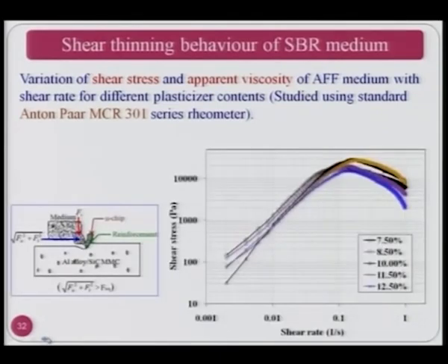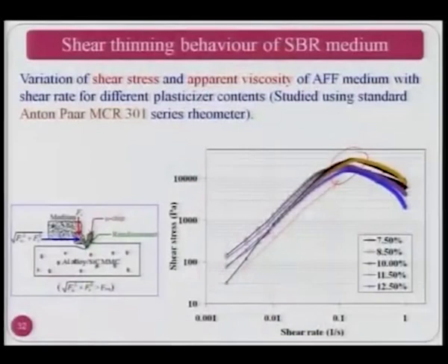see here a very interesting phenomenon, that as shear rate is increasing, shear stress of the medium, or the shear strength of the medium, is increasing. But when shear rate increases up to a certain value that is shown over here, then the shear stress or shear capability of the medium starts decreasing, and this phenomenon is known as shear thinning.